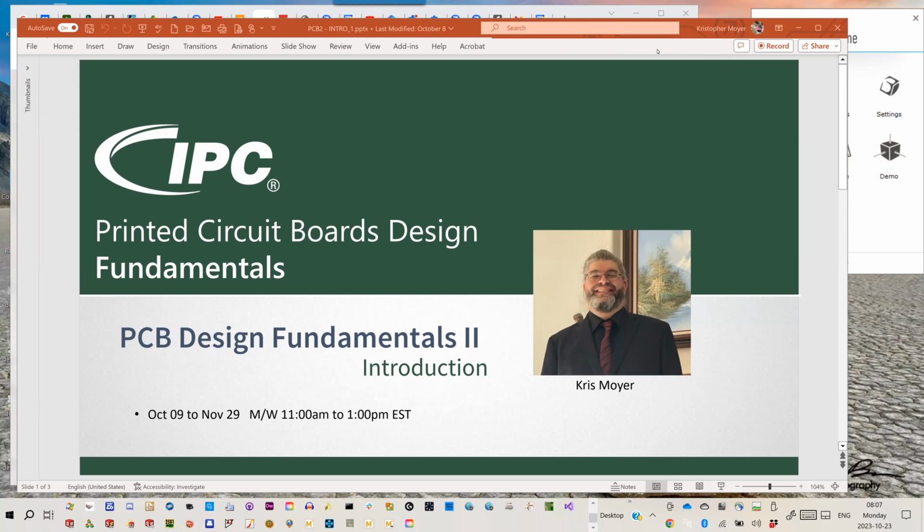With modern tools, all the big three, Cadence, Mentor, Altium, plus all of the second tier tools, KiCad, DipTrace, etc., all now support rule definitions. As long as you're meeting your rules, there is no reason to route on a grid. Now, grids are great for placement, but for routing, I always route as gridless as I can. I typically leave it on a 1 mil grid in my system, and that's usually sufficient.